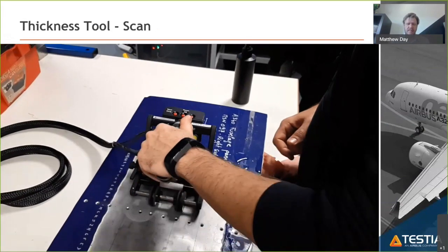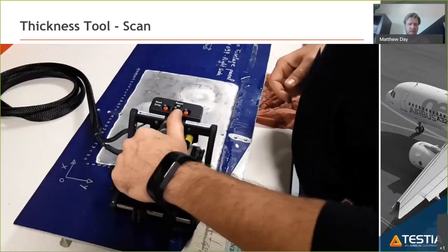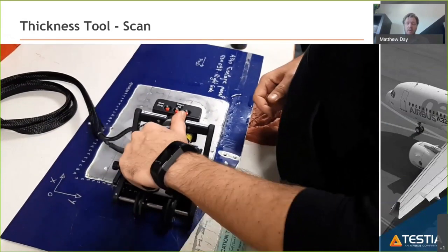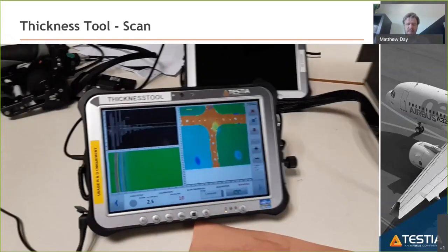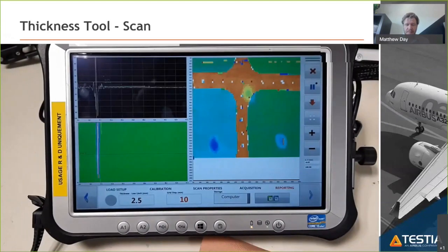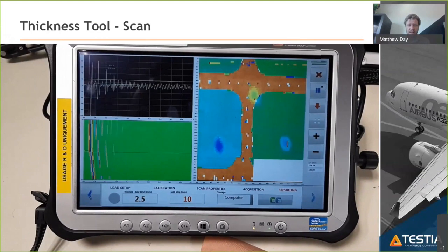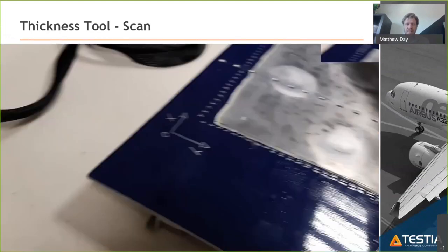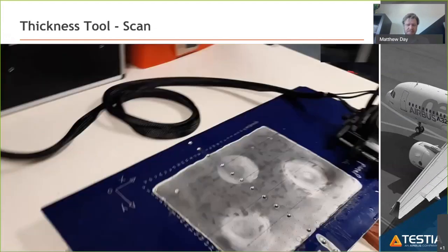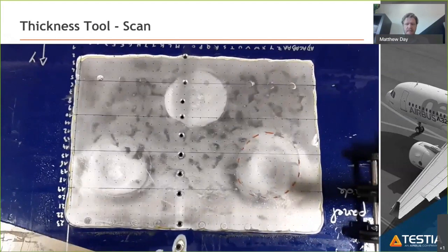He has already been provided with the grid measurements in columns and rows, and all he's had to do is measure out 45 millimeter wide guidelines, which the onboard laser lines track and allow you to follow neatly. And we can see very quickly, very easily, that we've been able to scan a very large area in a matter of seconds. We can see the 3 correlating defects, their blended out areas, on the screen.